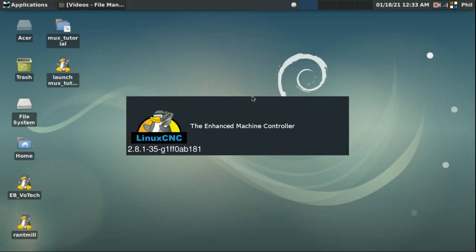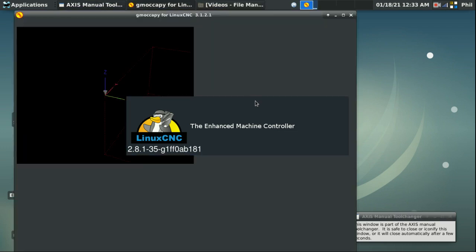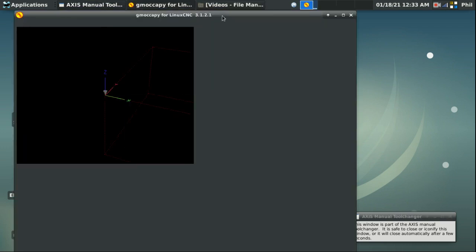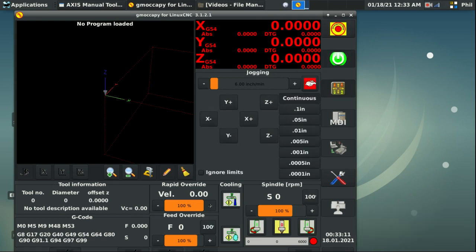So the MUX 8 command is a little bit more of the same, but now we're adding a third selection into our multiplex. And what that will allow us to do is use 3 wires to our breakout board and give us the option of up to 8 floating values within that MUX command.